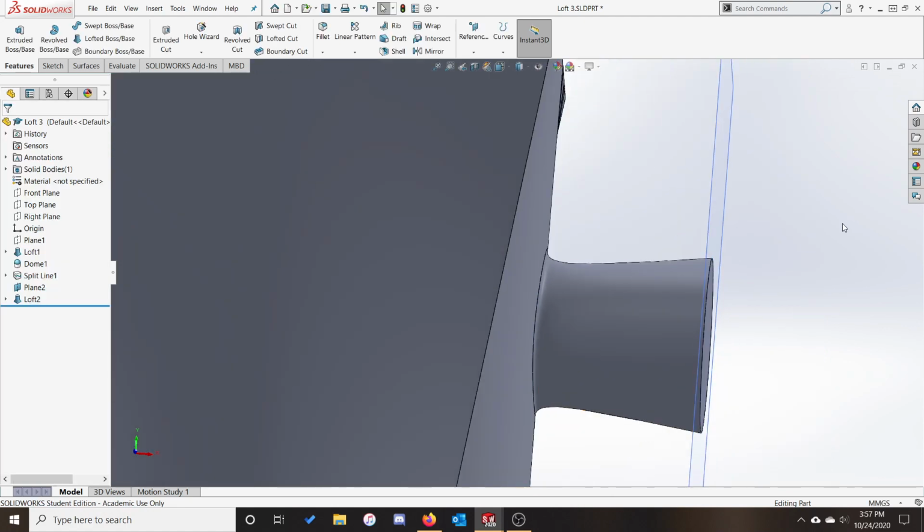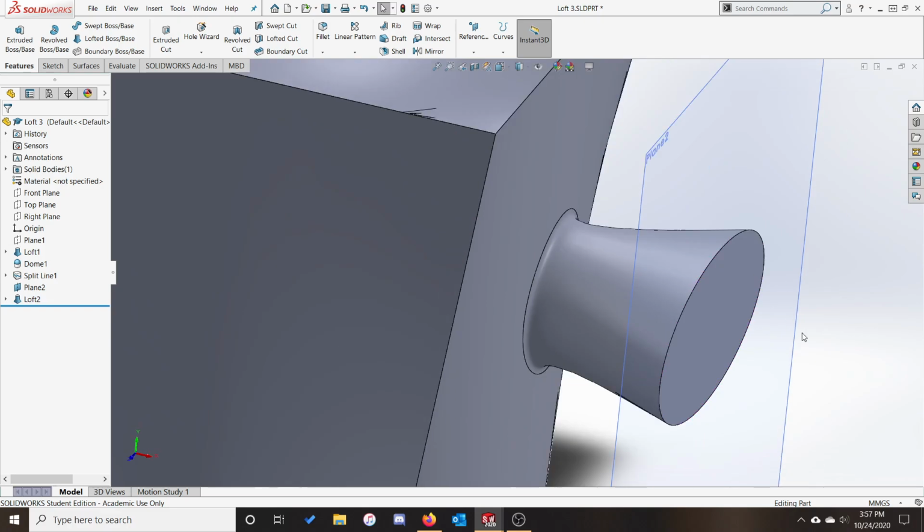One other thing that we can use these new faces for is coloring our part. SolidWorks allows you to change the colors of your models, but you can only select one color per surface. By using the split line tool, we can selectively color pieces of a face of the object, allowing more control over what portions of the initial surface are which color. We go into more details on our assemblies lab, and further on in the advanced visualizations video.